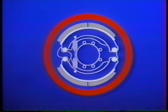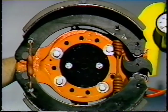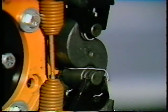But when a drum is machined beyond specification to solve a problem, the gap between the drum and new block is increased. And adjusting the brakes will only close the gap on the S-cam side, because the anchor pins on the other side are not adjustable. The inadvisable practice of installing oversized blocks seems to solve this problem. But since an S-cam is only capable of lifting brake shoes a half an inch, the block will eventually wear down and cause cam rollover to occur. The oversized blocks will have to be replaced before fully worn.